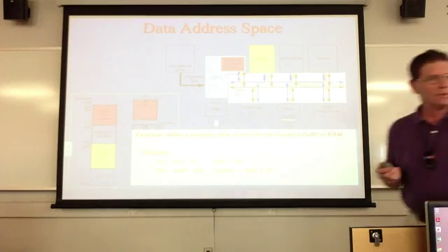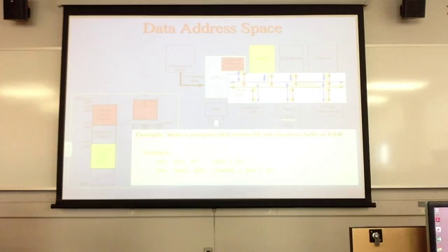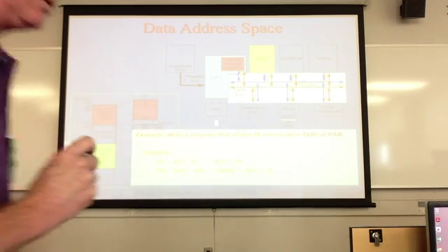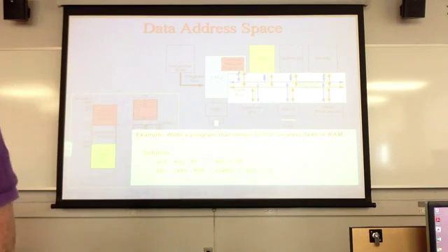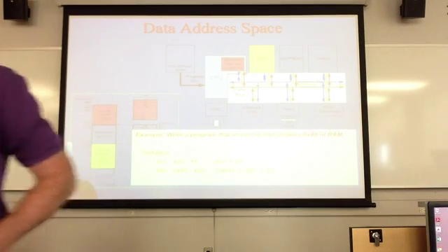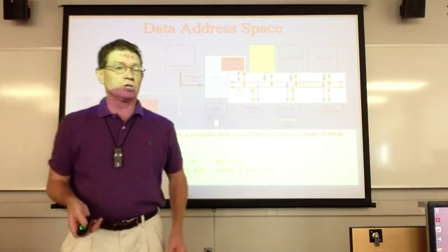Can you use the LDS also? Can you use either one? LDS, what's LDS do? Load data space. Could you use that instead of STS? What's the LD for? LD is loading to what? Where am I loading it to? Look at the opcode. You're asking, can I use LD to write to data space? Is that what you're asking? LD deals with what? Louder! Registers. All right? Then ST is to store to SRAM. No, really, it's a good question.